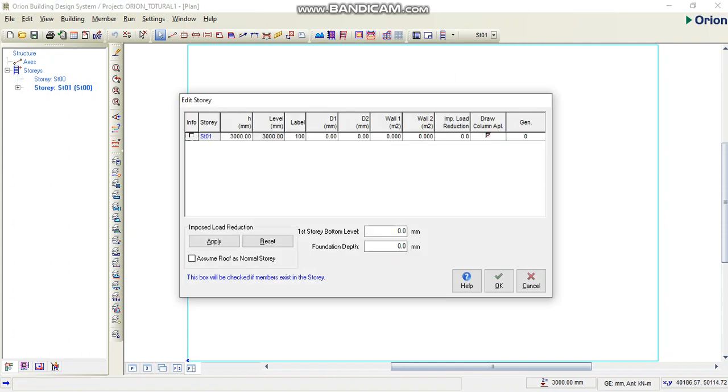Now this is where you're going to set your building height. Immediately you apply this setting, it will apply in other subsequent heights automatically. I love using 3.3 standard. Check foundation height. I'm going to be using 1000.